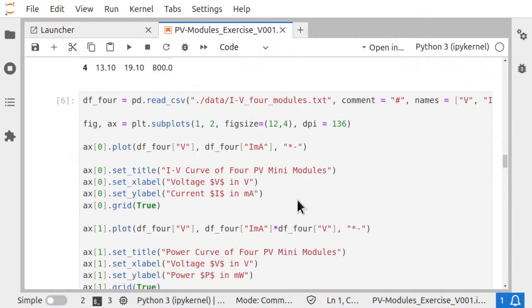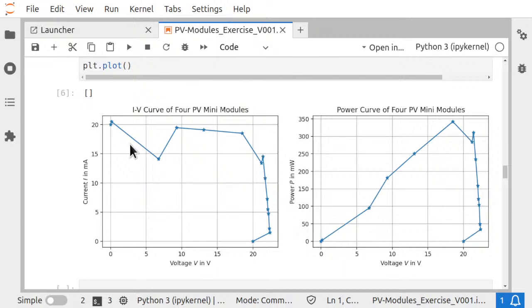Okay, good. So this is a performance curve of 4 modules in series. So I think what Jihad basically forgot was to substitute here the open circuit voltage. This is the old value which I initially added to the files, but you have to overwrite this, of course. So can you look up your notes? What was the open circuit voltage for this example?